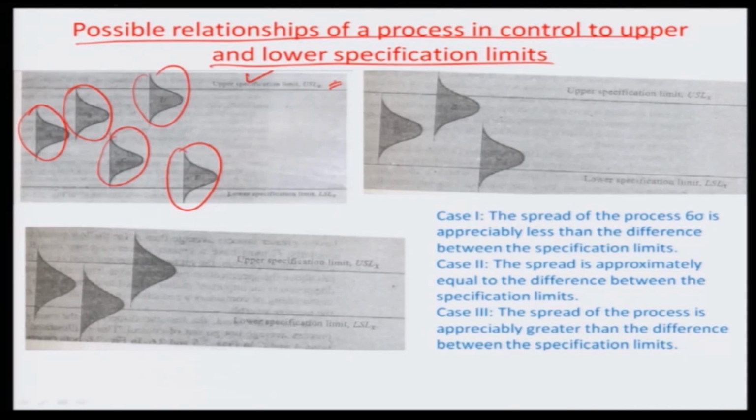Okay, and so therefore we can say that these processes are out of control, and there may be some rejections because of that. However, what is good in this process is that the dispersion and the mean are placed so that, with a little bit of process control, they can be well within the upper and lower specification limits. If the mean were centered around the specification mean, that would cause almost 100% acceptance, because there are hardly any values falling outside the upper and lower specification limits.